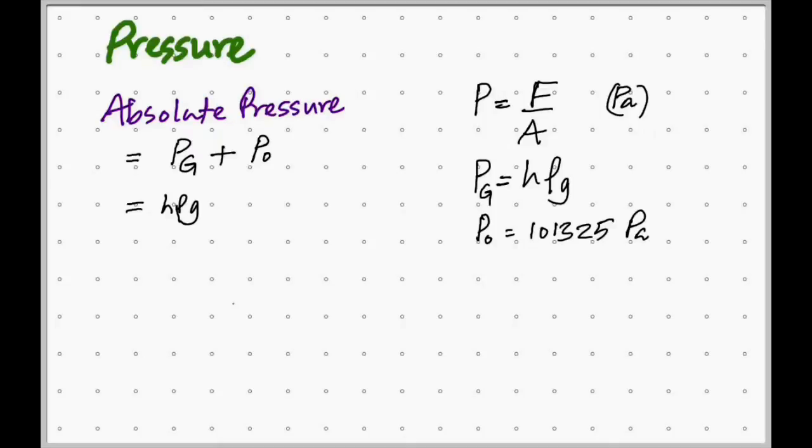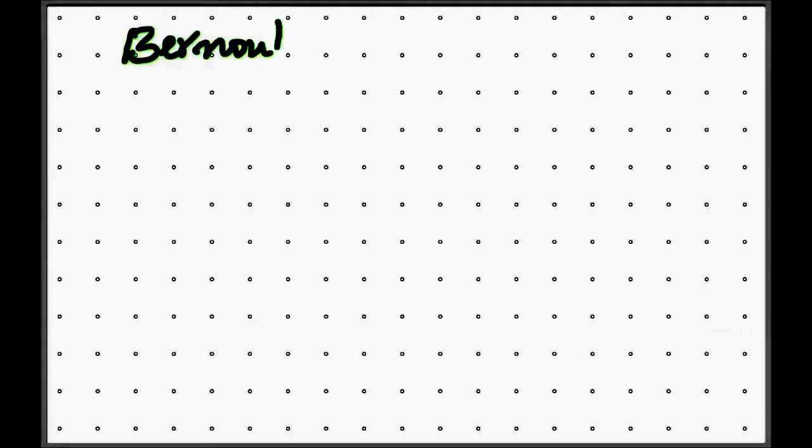Yes, then you'll have to subtract. Why? Because it's connected to Bernoulli's principle. In Bernoulli's principle, you first calculate the absolute pressure, and only then can you go to gauge pressure. I think Bernoulli's is coming. At that point, we'll go over that again, so we don't get confused here. I know exactly what you're talking about.